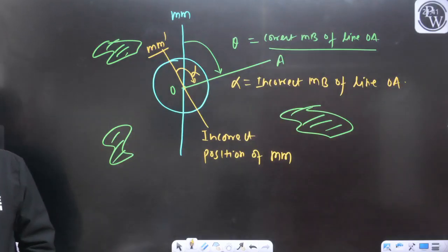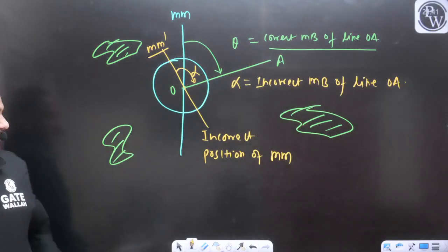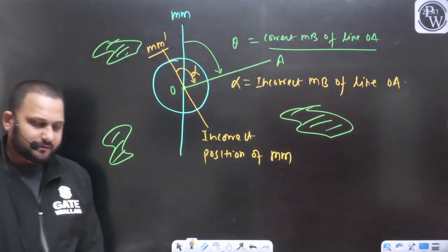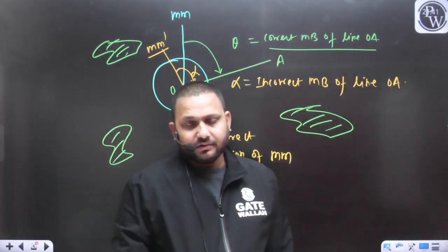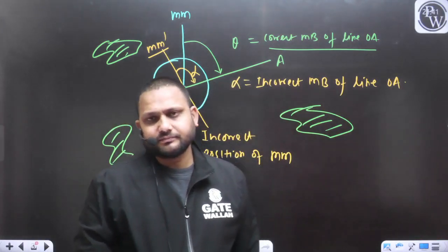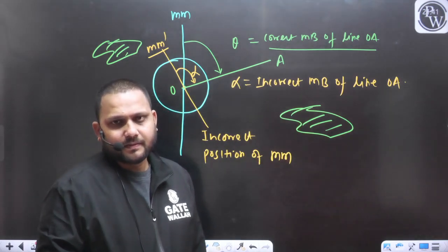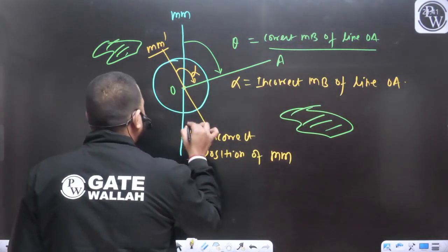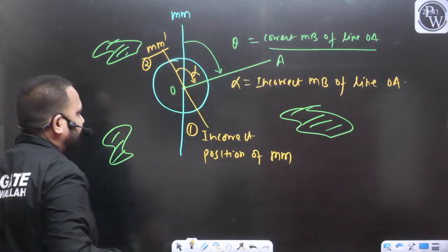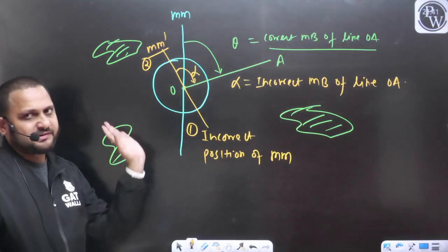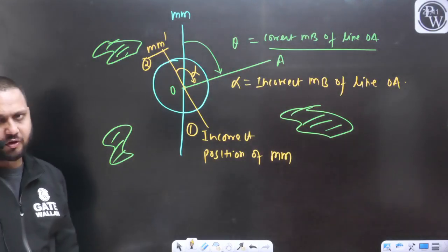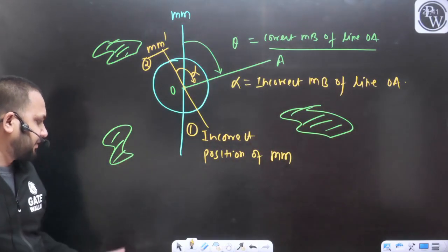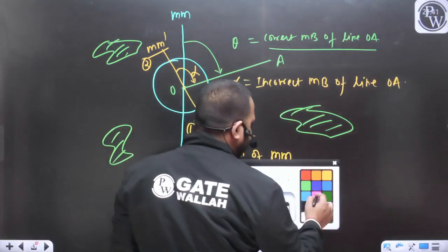If our reference is not correct, how can we measure the correct bearing? So let's say this is the case 1 that we have discussed. There is no such fixed point that we will always get the magnetic meridian on the eastern side, on the western side, sorry. Under the influence of these objects, you may get the position of the magnetic meridian like this.